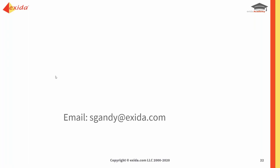We have a lot more guidance on proven in use. And again, we go through this in some detail on the FSC 100 course. So we explain what you need to do for proven in use justification for a SIL 3, which is very tough. If you don't use certified devices, then you're going to find that's a very tough one to meet the SIL 3 requirements.